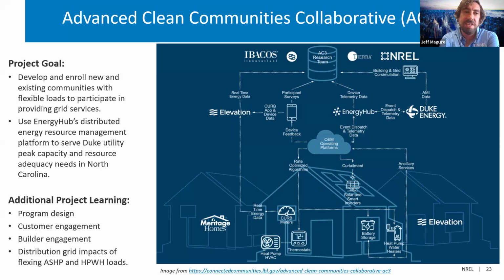This project is looking at what the potential benefits of all that control are in coordination. We're using OCHRE to look at what it would look like if everyone's participating, and the potential response to different control signals. One thing that's particularly of interest in this project is if you have air source heat pumps with electric resistance backup, sending different thermostat signals might actually trigger that backup more frequently, and so you end up creating these unintentional peaks in the load.